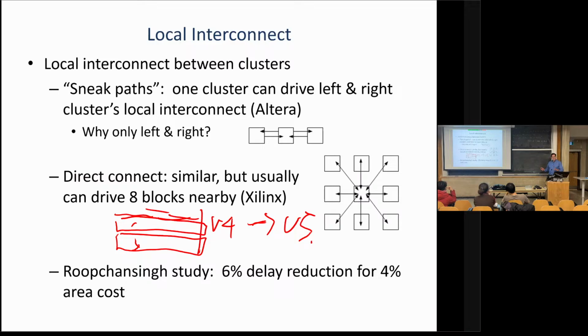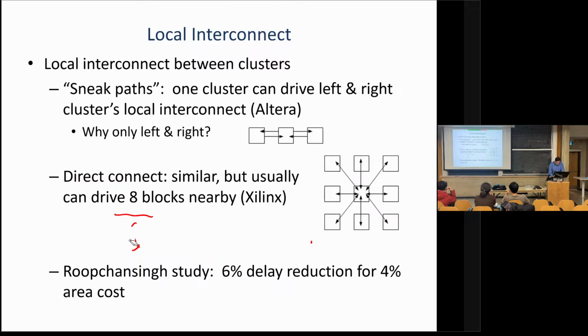Does that make sense? So, but what this means is that your vertical wiring is fundamentally more expensive than your horizontal wiring. It's always 1 unit longer than you told the end user, and there are a couple ways to do it, but the basic way to do it is you make tri-states on the vertical wires. Okay, so they can actually be driven by 2 rows. Okay, so you can't use a full direct drive on it. There's actually a way to do that, but it's super complicated, so I'm not going to tell you that. The basic way you would do it is you make 2 drivers. That actually makes your vertical wiring more expensive.